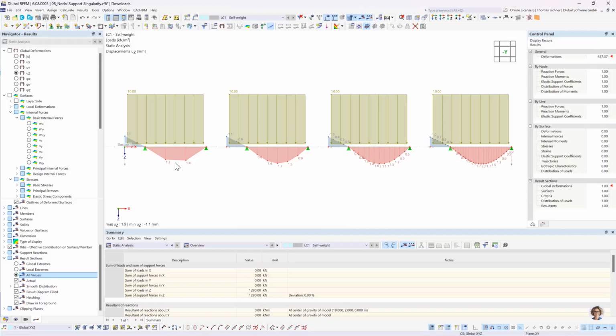This 1.7 millimeters would be in between this 1.3 and 1.4, but we don't have a result there, which means we just forget some internal forces to investigate. That's a big problem. So we need to have at least 1 or 2 points in the vicinity of these maximums.